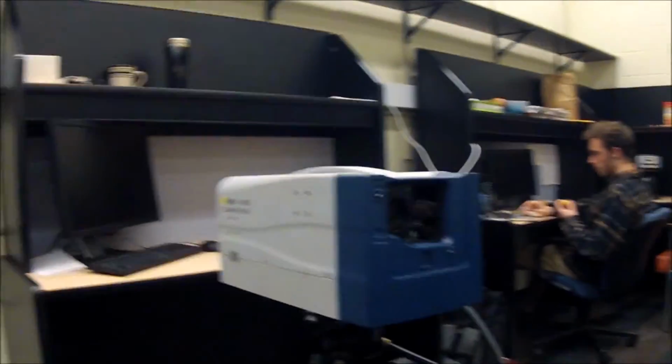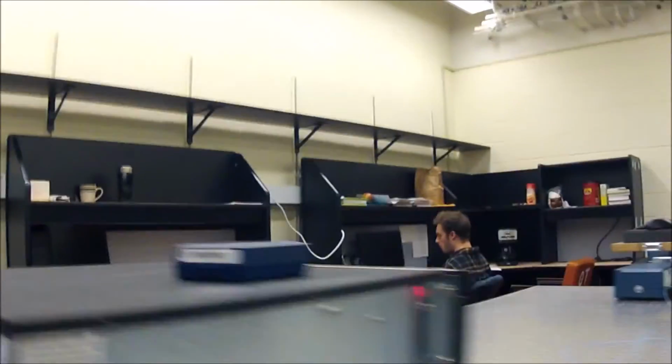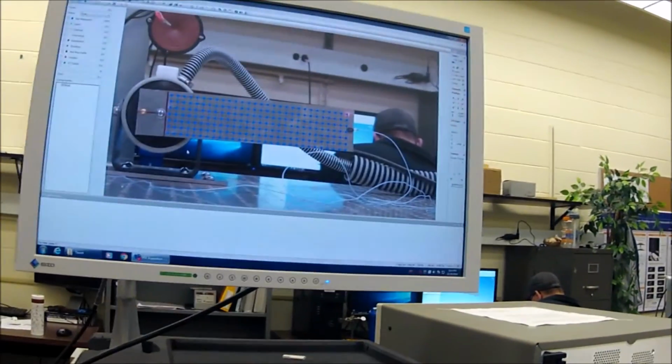The second part is to take each natural frequency and send a constant signal to the beam. The scanning head then uses a mesh of 29 by 7 points to obtain the displacement values at each node. The vibrometer checks to see if the node is optimal. If not, it rescans. Then the computer creates an animation of the vibration mode.